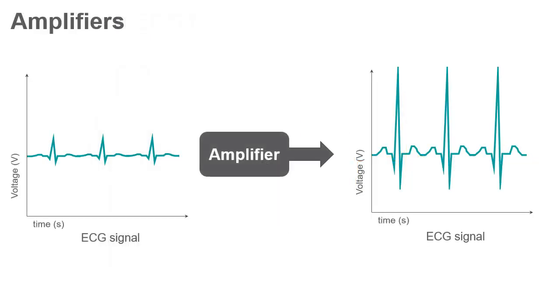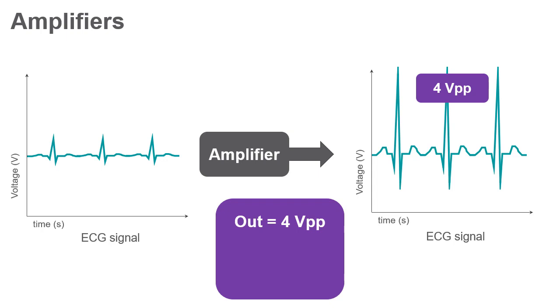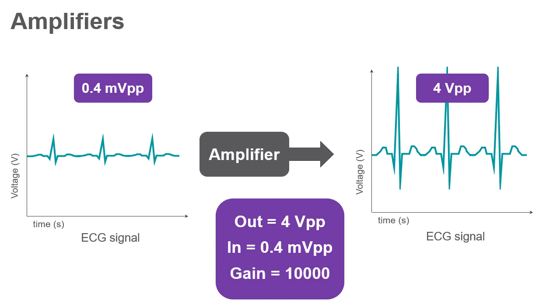Amplifiers. Amplifiers convert energy from a power source to increase the amplitude of an input signal. A common way to rate this magnification is the ratio of voltage measured at the output port to voltage measured at the input port. This ratio is typically referred to as gain. Let's look at 4 types of amplifiers: inverting, non-inverting, differential, and instrumentation.